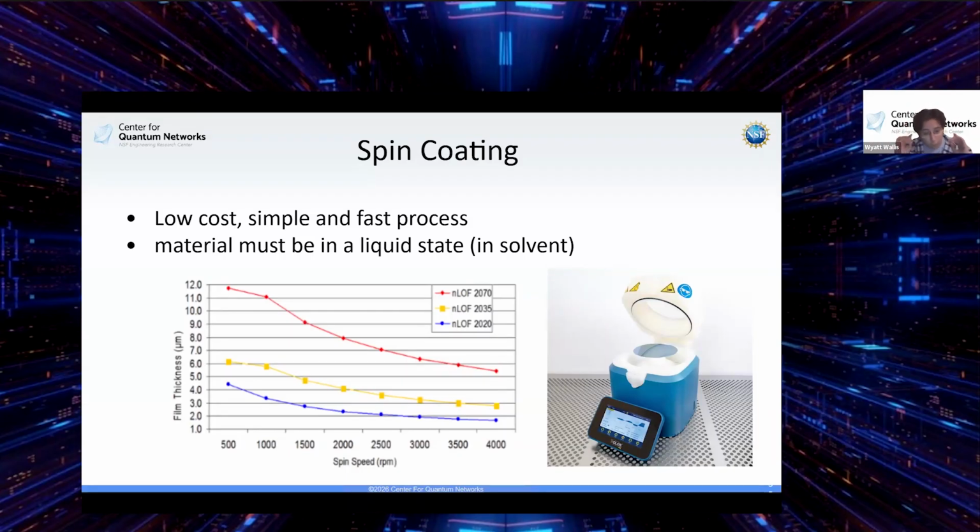If you're working with especially a novel material or material you don't know, this is where one of the biggest things I always tell people: always make sure you have extra samples. That way you can test out a couple things, maybe 3 or 4 times on small samples, and then look at what the film thickness is using some profilometer. Because when you have the film thickness and you know how much you spun it at, you can make your own spin curve. So always make sure you either have a spin curve, a known spin recipe, or you make one.